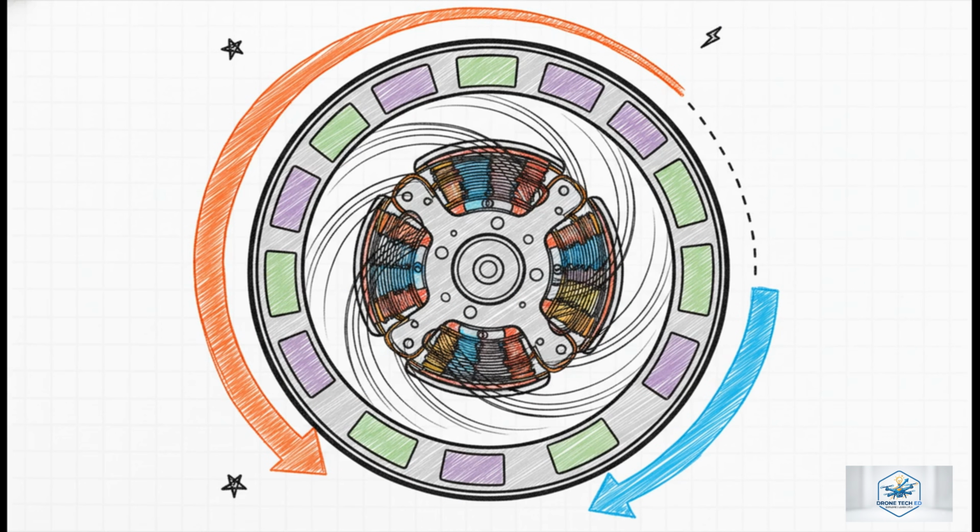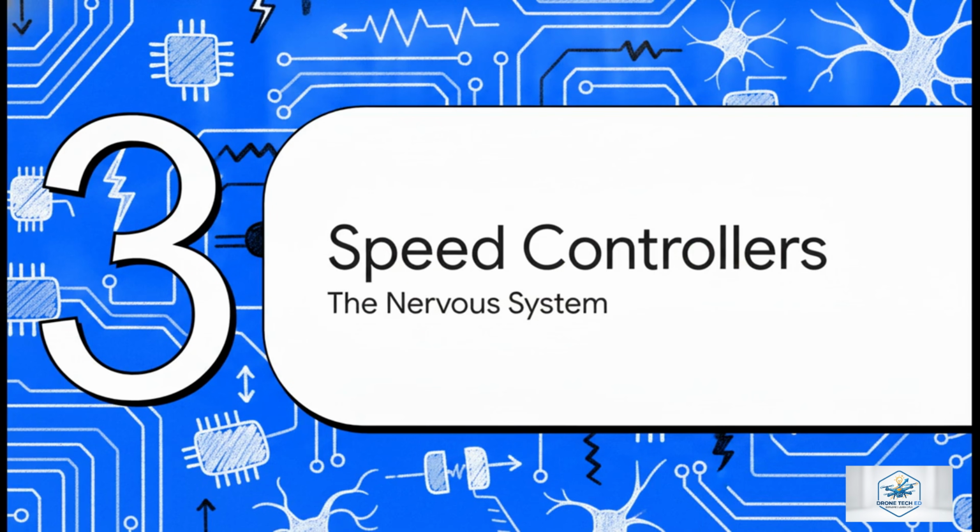To actually make these muscles contract, we rely on some pretty deep math. The stator inside the motor generates a mathematically perfect rotating magnetic field using 3-phase alternating currents. The resultant magnetic flux maintains a constant magnitude of exactly 1.5 times the peak flux of a single phase. The permanent magnets on the rotor are continuously chasing this rotating field. It's honestly exactly like a greyhound chasing a mechanical rabbit around a track, and that endless chase produces perfectly smooth, continuous torque.